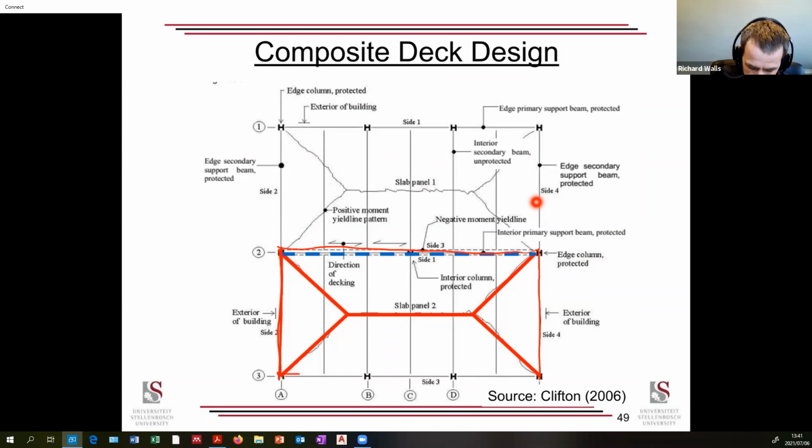You would design as if the whole slab in the middle has failed, and you would not protect all those beams. They would be unprotected. You do not put a stitch of passive protection. You let them fail. You design it using a crack pattern, so traditional failure patterns, plastic analysis with catenary action involved, and you save 50% on your passive protection cost, relying on your perimeter beams and relying on your columns.